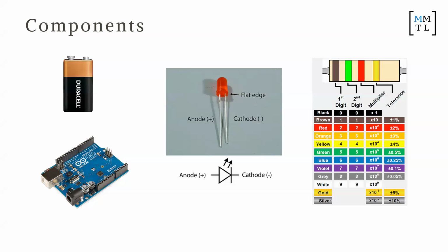Oh, it has 10% on it. So just keep in mind resistors are made imperfectly, and so there's always a tolerance. It's never just perfectly 330. It can be 5% higher, 5% lower, 10% higher, 10% lower, depending on what's printed on the resistor. As you can imagine, the lower tolerance you get, the more expensive the resistor gets, as it's almost near perfect.